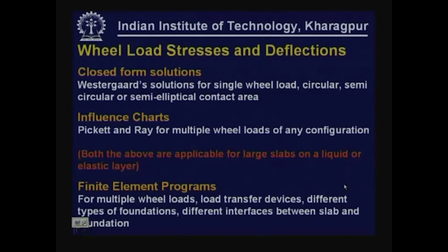Closed form solutions are given by Westergaard for a single wheel load, with circular contact area, semicircular contact area or semi-elliptical contact area, but circular contact area is the most commonly used shape of load contact. A number of influence charts are also available, by Pickett and Ray, providing solutions for multiple wheel loads of different configurations. As we know, the load contact area is not in general circular in shape.